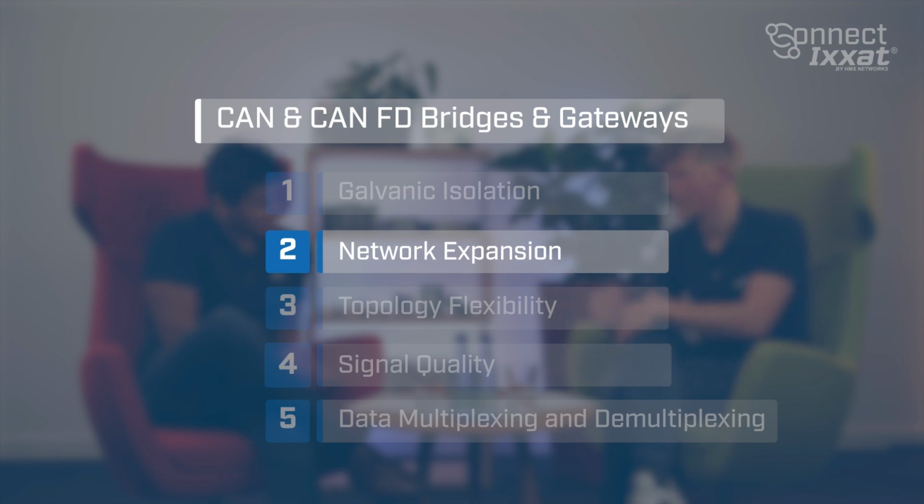The next one is the range extension for CAN, but specifically for CAN-FD. And there are two options here for these bridges and gateways. The first one is using a CAN bridge. This is a CAN to CAN bridge, and this will actually double your bus length. The second option is using a CANetNet, which is a CAN to Ethernet, and then again to CAN range extension. Here it is really dependent on the application, if you're doing real-time stuff or not. But in general, it's just routing a CAN message over an Ethernet network, and then it's unlimited, could be within a building, could be wirelessly to a different continent. So here, the imagination is the limitation of the use cases.